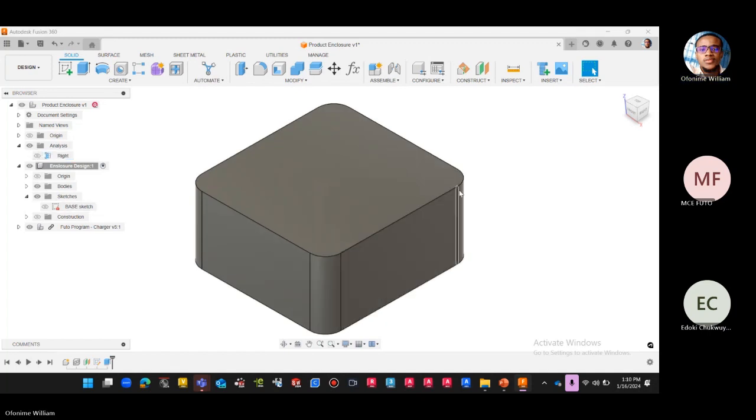And then the next thing we probably want to do, since we've extruded, we probably want to do what? A filleting with chamfer, and then we shell. Now take note of how I'm going about it. Chamfering, or chamfer, fillet, then we shell. Now the first two, the chamfering and the filleting, are related to the additive manufacturing we talked about, right? The reason why I'm bringing it in. Are we good? Now, the one that has to do with the shelling coming later has to do with what? You being able to achieve your end goal in this workspace.